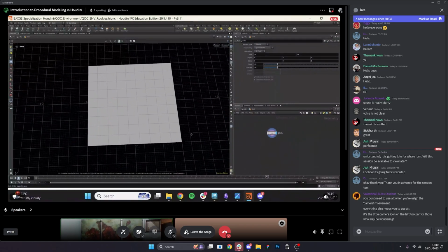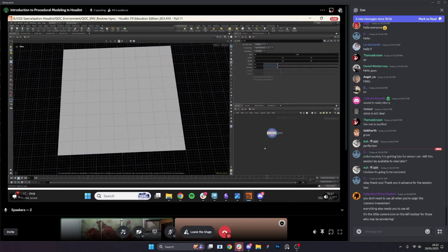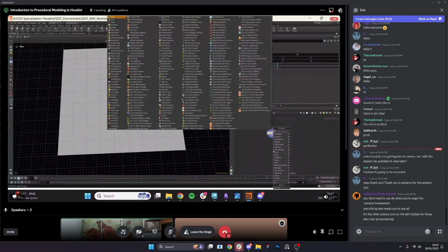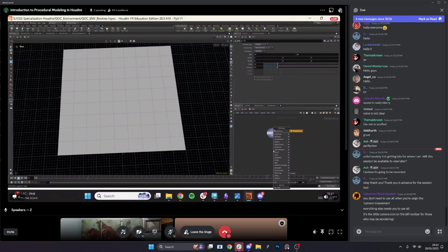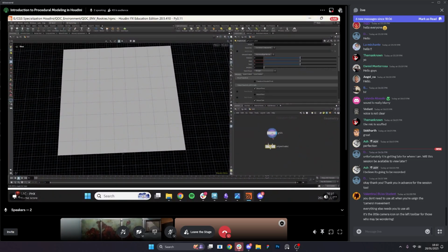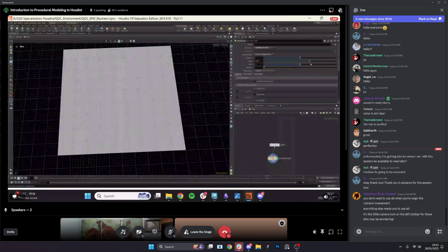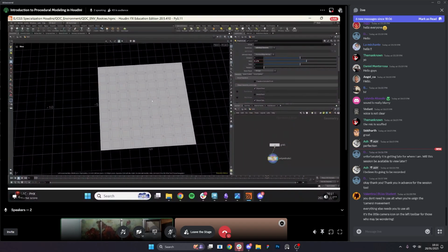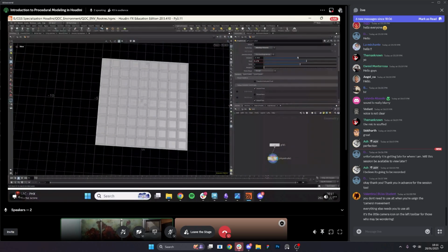our aim is to inset each of these squares individually. But if we use our extrude node, which is a poly extrude, by default it insets the entire thing, which we don't actually want. So we're going to change it to individual elements. Now if we inset it, it'll inset them as individual elements. Couple of other things you can do here. You can adjust the distance. You can twist it.